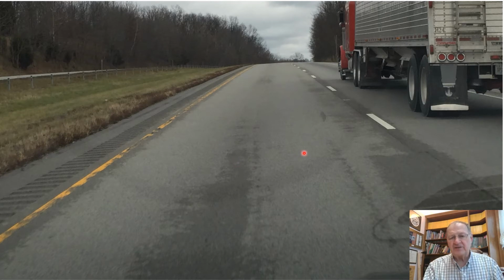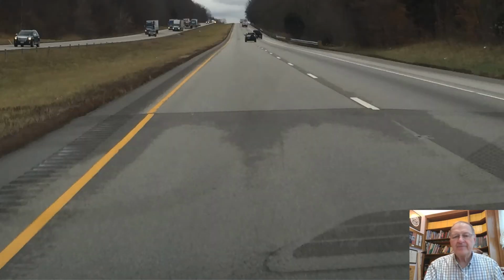Well, what else do we see? Here's a crack. And then this crack disappears. Why does it disappear? It's because the density is higher, the permeability is low, and the pavement did not age. So this slide gives you an example of what happens when we have high in-place air voids or low density. By the way, end of the patch, same thing.